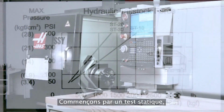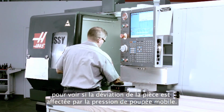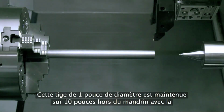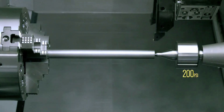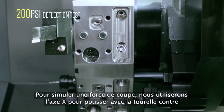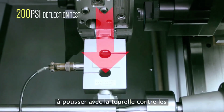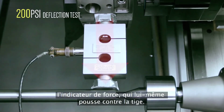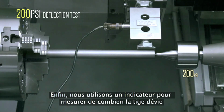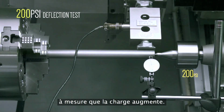Let's start with a static test to see if part deflection is affected by tailstock pressure. We've got this 1-inch diameter shaft held 10 inches out from the chuck, with the tailstock clamping it at 200 psi. To simulate a cutting force, we'll use the x-axis to push with the turret against the load cell, which in turn will push against the shaft. And finally, we'll use an indicator to measure how much the shaft deflects as the load increases.